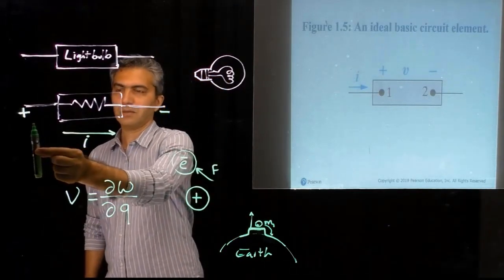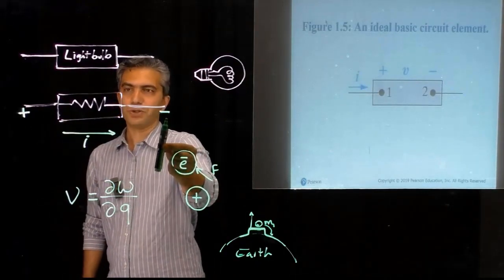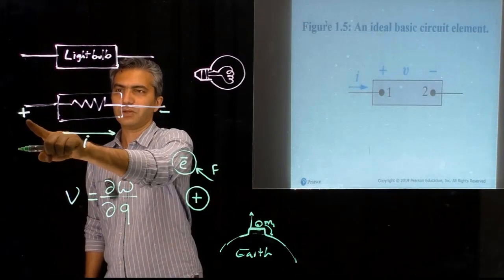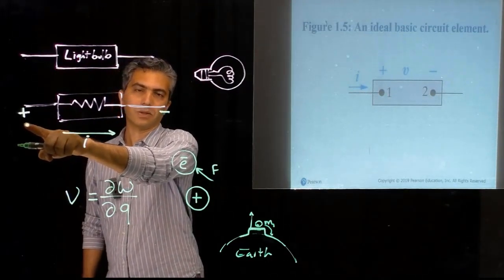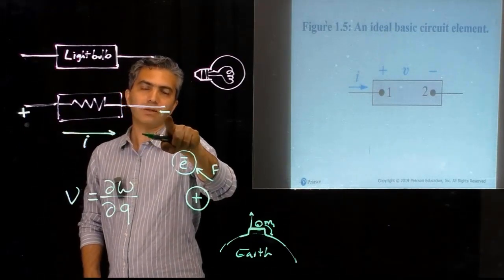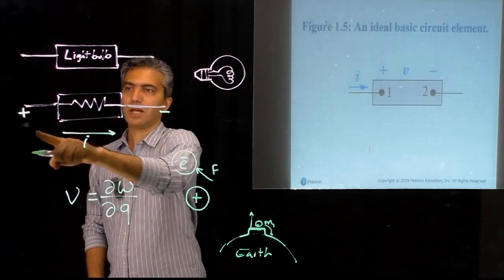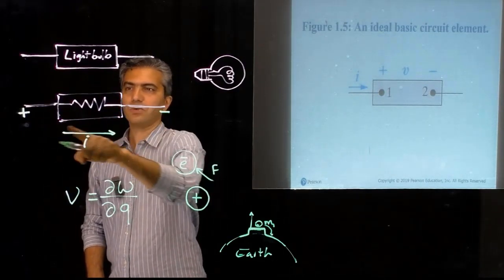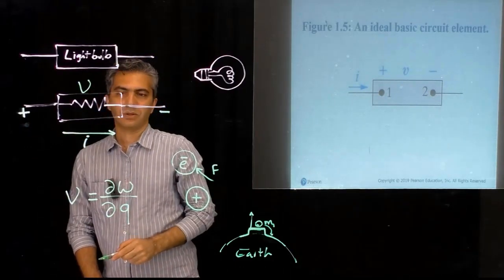And with that comes the differential definition of voltage. If you take the potential on one side, or at a certain node in a circuit, or a certain node in a component, and you assume that the reference for that potential is the other side of the component, you can take the difference between the two potentials and define something that we call a voltage.